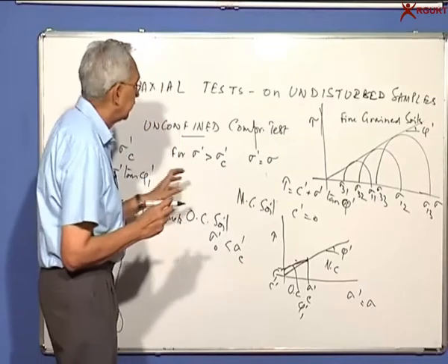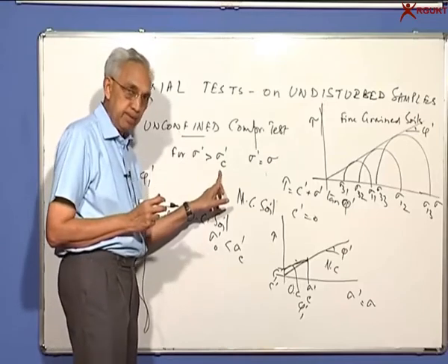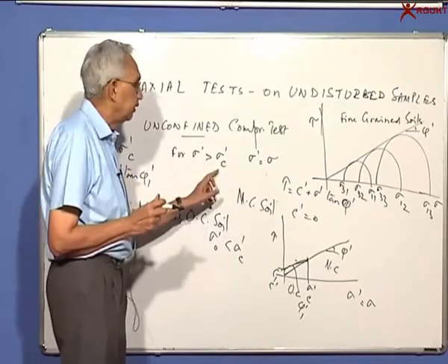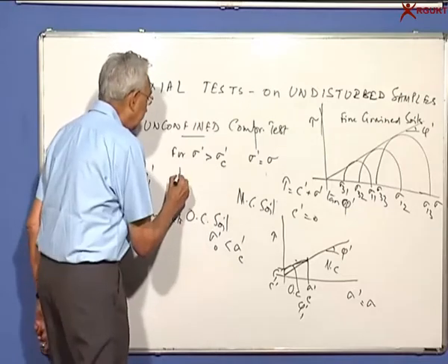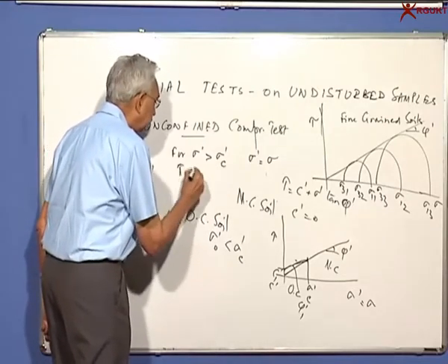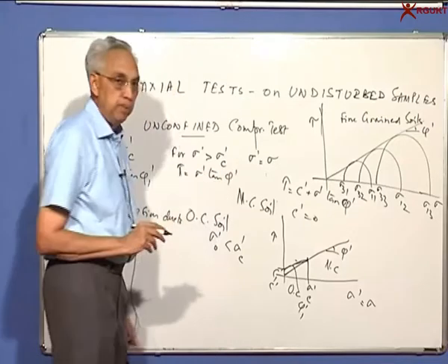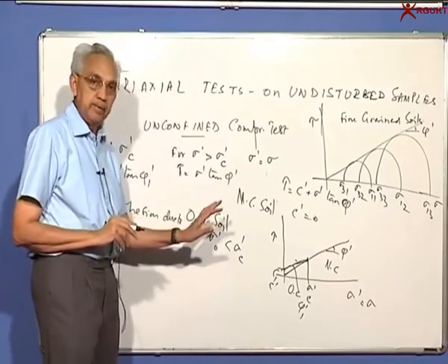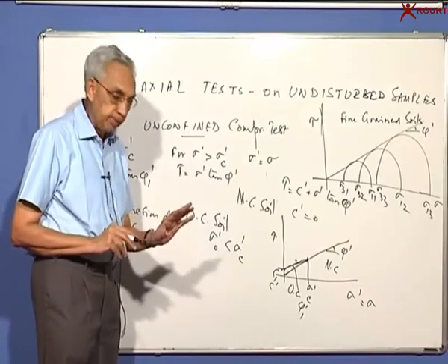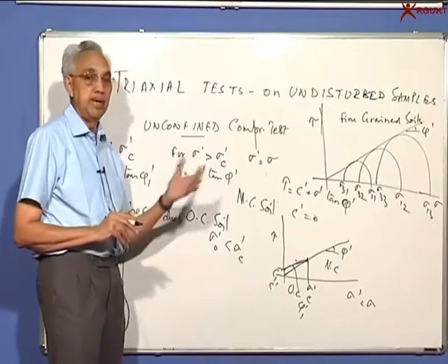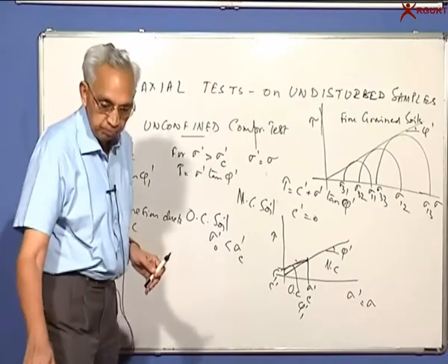Because of these, the over-consolidation effect has come in, but now you are applying a stress higher than the maximum past pressure, then it behaves like a normally consolidated soil. Please remember, it doesn't matter even if it's over-consolidated, but the stresses we are dealing with are beyond the maximum past pressure.